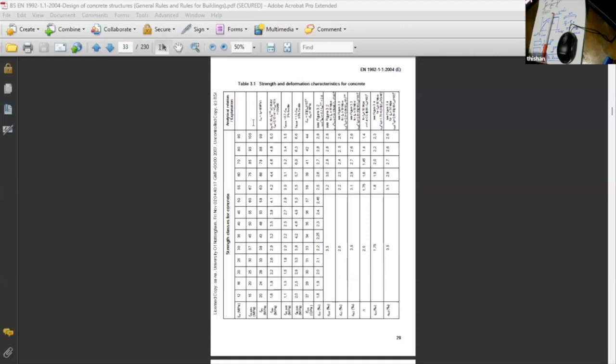Well, we had a problem. The costs were too much. Projects were becoming not feasible. So what we have done is, we have changed the foundation, done a more advanced design. But you might ask, how are you going to ensure that it's going to work? It's so simple. For piles, we have PIT, pile integrity test. We have PDA, pile dynamic analysis. We have maintained load test.